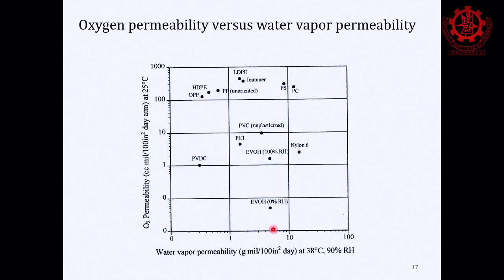But definitely the permeability is affected by temperature. So the higher the temperature, what will happen to permeability? Higher permeability. Why will it be higher? What happens to the polymer if you increase the temperature? What could happen? You would increase the space between polymeric chains. If you increase the space, then it's going to allow more gas to transmit.